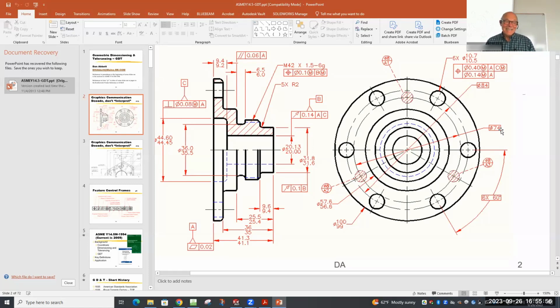I mean, it's a weird thing on a drawing because you cannot put a tolerance on a box dimension, on a basic dimension. But you have to have tolerances on every other dimension. You take a tolerance like over here, if that was 44.45 with a box around it, it means as close as you can make it with the best equipment, the best machinist that you have.